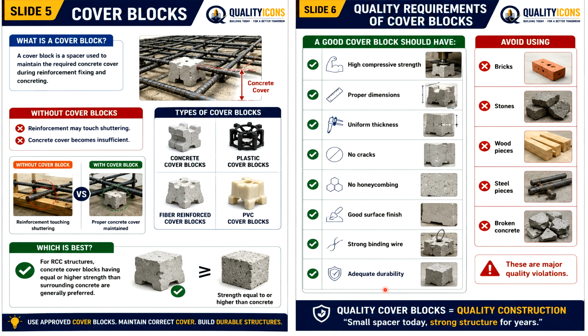One example. Sometimes contractors purchase low quality cover blocks. During reinforcement fixing, workers walk over them, and the cover blocks immediately break. What is the use? Now, reinforcement rests directly on shuttering, and the entire cover requirement is lost. Always inspect cover blocks before use. Reject cracked or damaged cover blocks. Never use them.